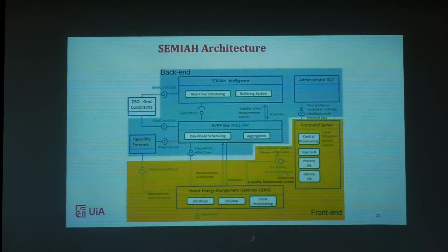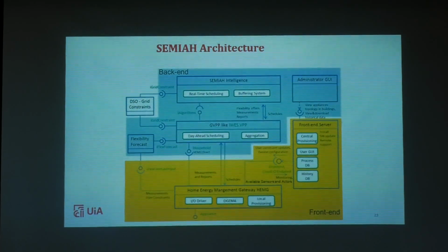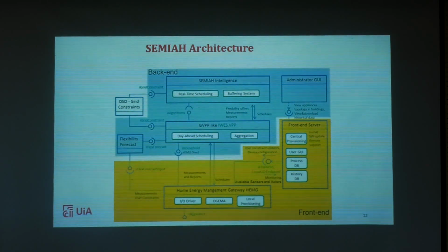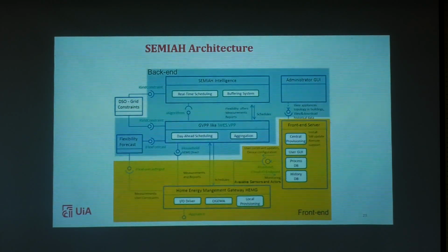So, when we are selecting some of the appliances, let us say we are taking thermal inertia based load or the boiler, for which the complete mathematical modeling of that boiler will be required, because that boiler has some constraints for minimum operating temperature, maximum operating temperature, its input power, as well as from its output how much water we are consuming.